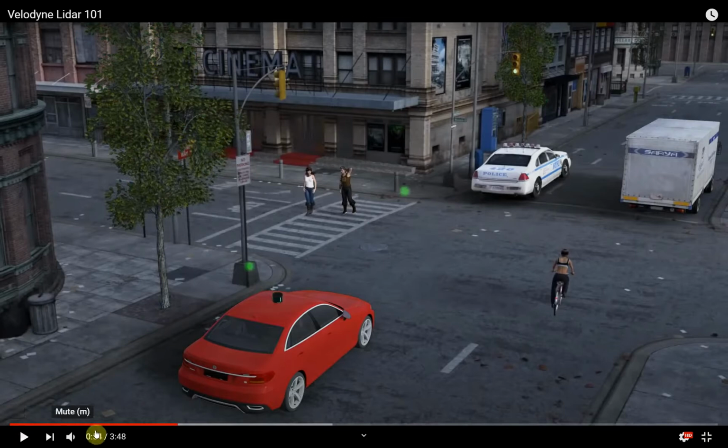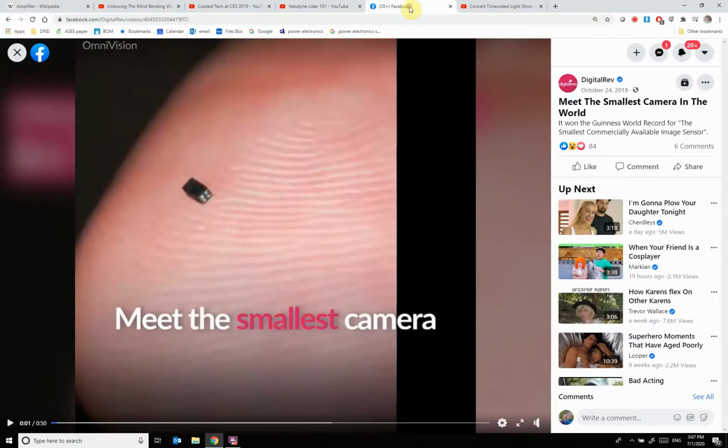Okay, so in this LiDAR application, you can see that a light goes out, hits something, and that light basically scatters everywhere, and you pick up a very small amount of it. You have a narrow pulse going out and coming back and timing, and all that requires lots of amplifiers. So the amount of light that you're going to receive back by sending out a small pulse and then letting it scatter everywhere is going to need really good amplifiers. So the better your amplifiers are, the better your LiDAR systems are.